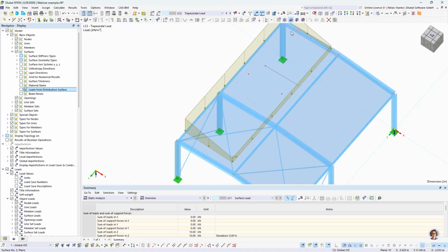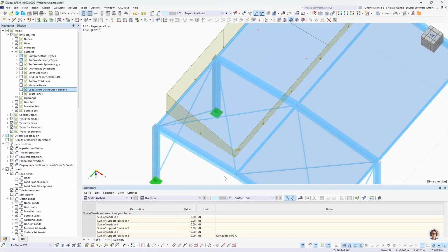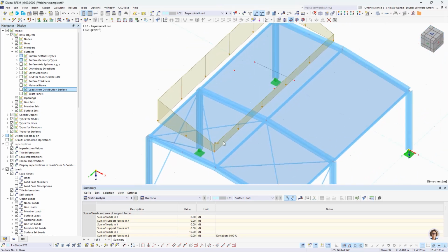So you can imagine, like, if there would be many single beams which are lying in this direction on the roof. And every one of these beams or every one of these stripes is loaded with this trapezoidal load. And always if such a stripe cuts a member, like for example these rafters or also the horizontal bracing, then these members will be loaded by the stripe.